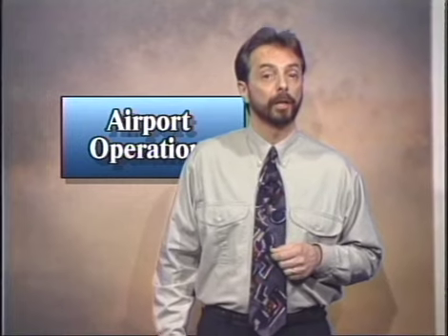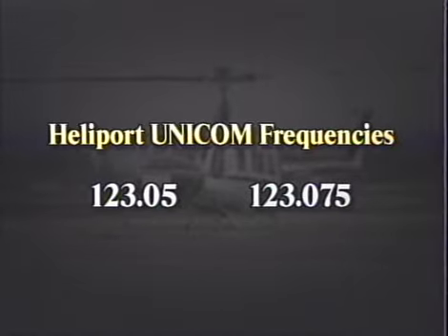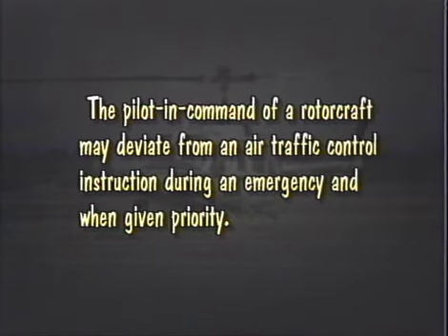Prior to approaching such a heliport, you'd probably want to monitor the radio traffic and call ahead with your intentions. The Unicom frequencies normally assigned to heliports are 123.05 and 123.075 MHz.